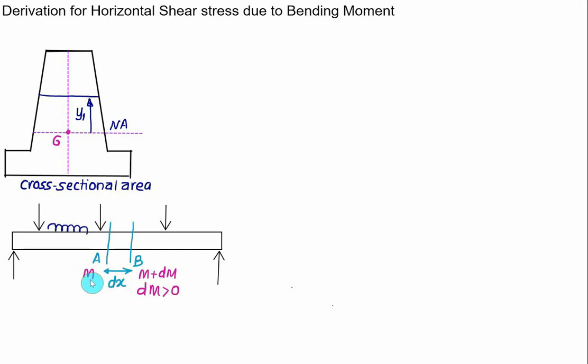So we have to show one bending stress distribution for the section at A for the given cross section. The top fiber is away from the neutral axis, so maximum bending stress will be developed. Let's assume it is tension and is a maximum on the top fiber. In that case, at the bottom we have compression, and the distance of the bottom fiber from the centroid is less compared to the top fiber, so we have a smaller value of compressive stress. So at section plane A we get the bending stress distribution here.